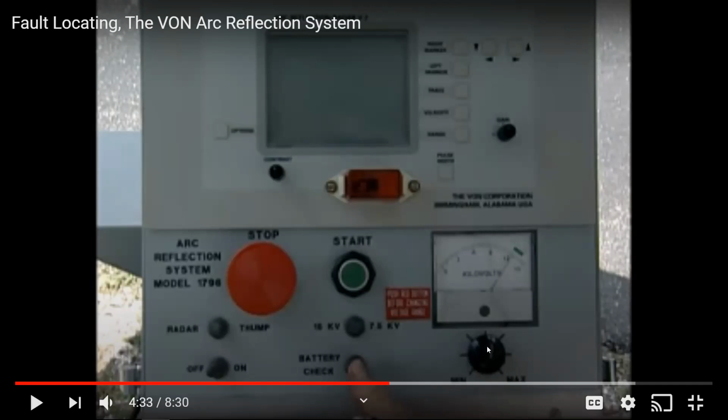No, well, what it does is it messes up the capacitor inside. You have to stop the machine, readjust up, start again. If it's still not high enough to what you're desiring, stop, adjust, start. That's the same way up and down. Do not adjust this while this red light is on. It will destroy the machine.